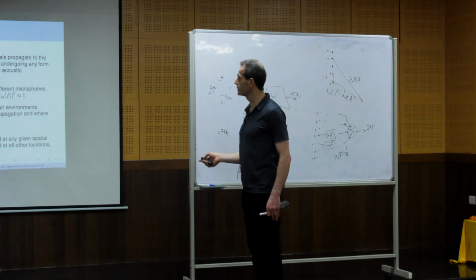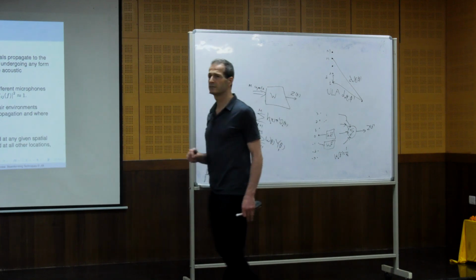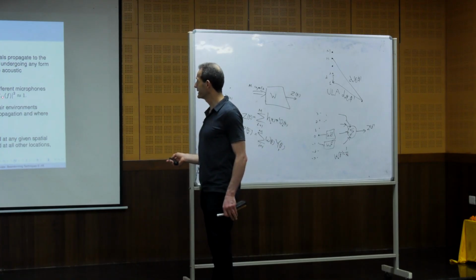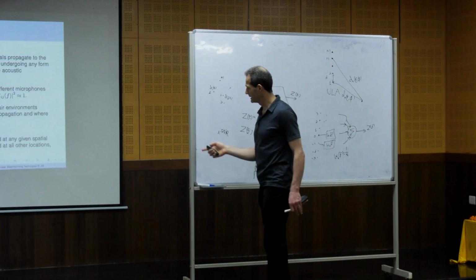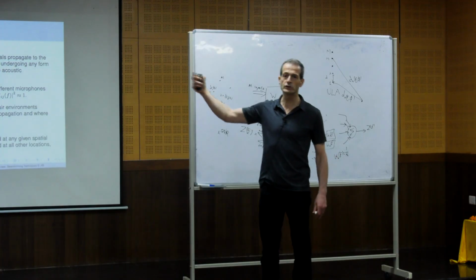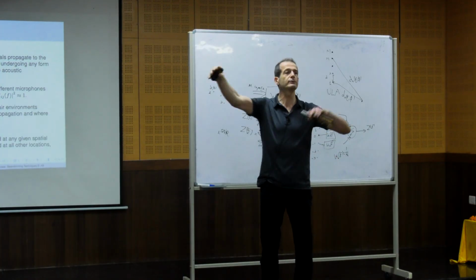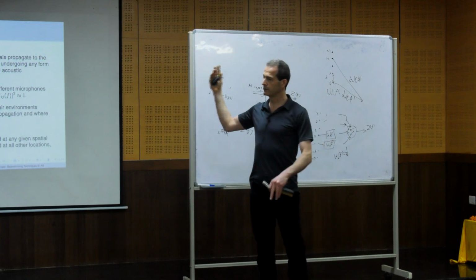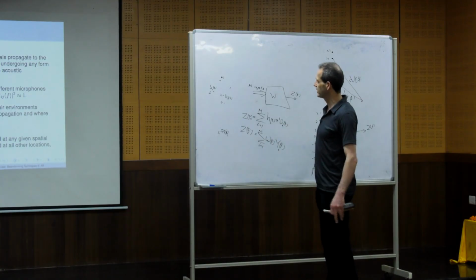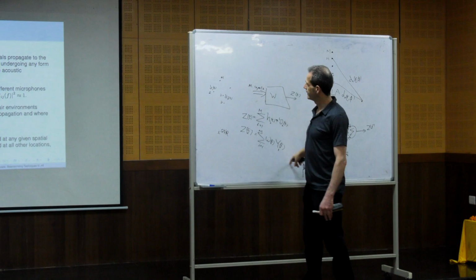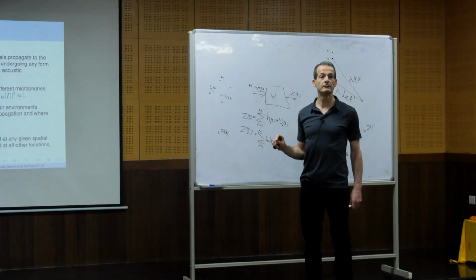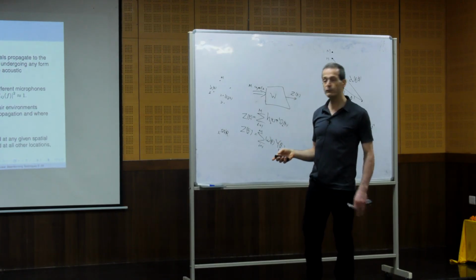For coherent noise fields, the magnitude squared coherence between any two sensors is very close to 1. This is obtained when we have a noise source or interference without any reflections. If we have a noise source and no reflections in the environment, it is measured by each sensor with a simple delay.